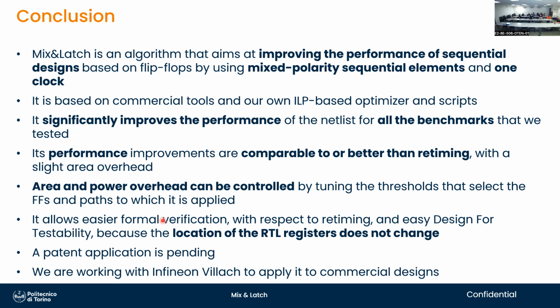Yeah. I mean, you can always spend the same amount of time doing your RTL design, and then get better clock frequency, or spend less time and still get a decent frequency, the same one that you could have achieved by manual balancing of the stages in a shorter amount of time. That's always possible. It works both ways, to shorten the design cycle or improve performance at the same design effort. Just like HLS, by the way, same thing.